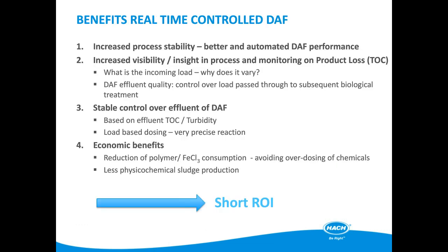When real-time control is applied to the DAF process, the software adjusts the process parameters to suit the incoming load, and by incorporating a feedback element, any variations in the process efficiency caused by variable chemical quality can be compensated for. RTC also provides the operator with information on the incoming load, indicating when peaks are occurring and when upstream processes may indicate issues. Stability of the outlet load also gives a stable cost for further treatment or charging.